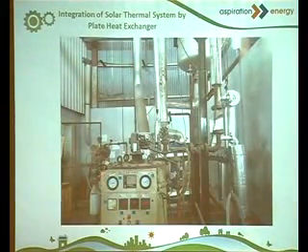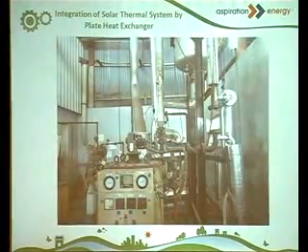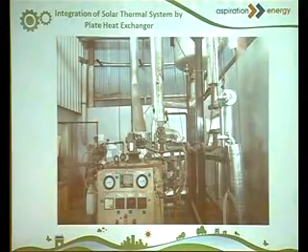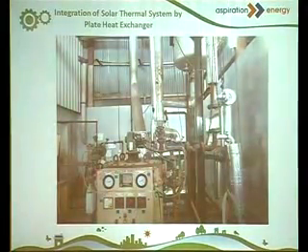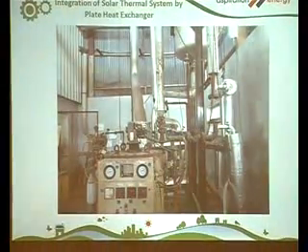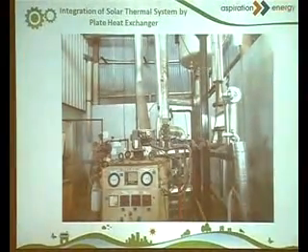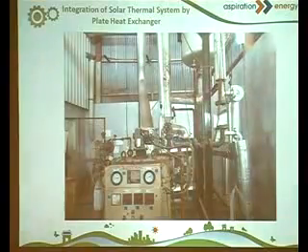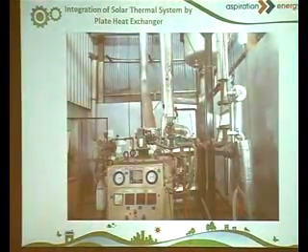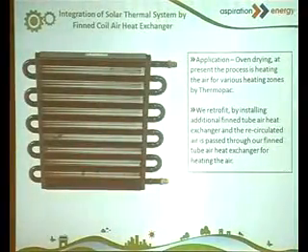But in many industries, wherever they are using hot water generators, we find that such systems are already in place. The heat transfer is not in the tank but in an external exchanger. It becomes very easy to integrate in those cases. Although it is complicated, the complication is already handled by the existing plant. So all we need to do is interrupt the flow from the existing hot water generator and insert our solar coil, and she will show you a couple of schematics on how that works.